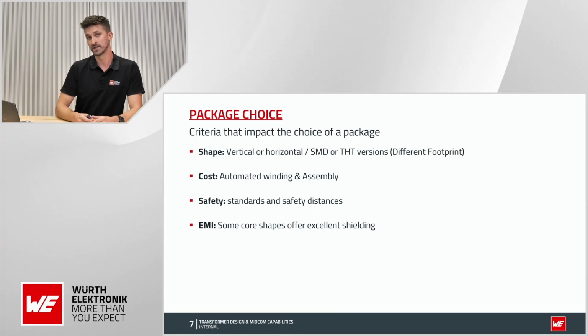And then if you need to achieve some EMI compatibility in your parts, we have some core shapes that offer a better shielding solution than others. Of course, the power is very important to know, because the power at the end will determine the package and the overall dimensions of the part. And it is, of course, probably the most important information we need to know.